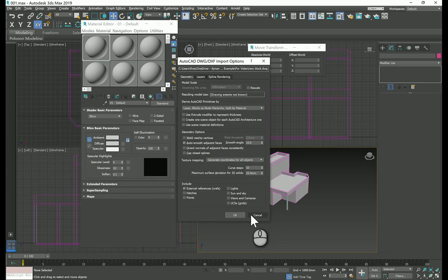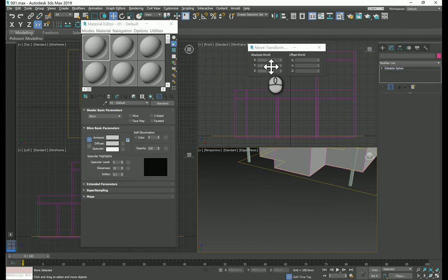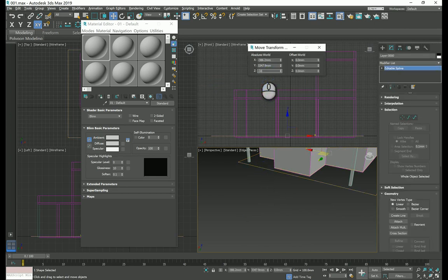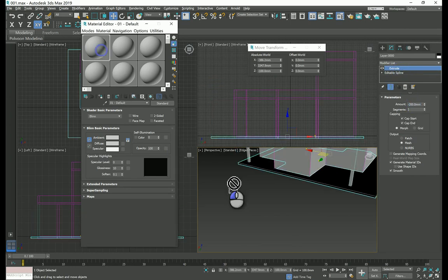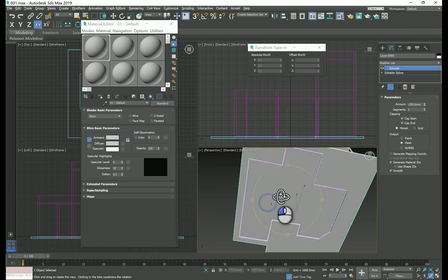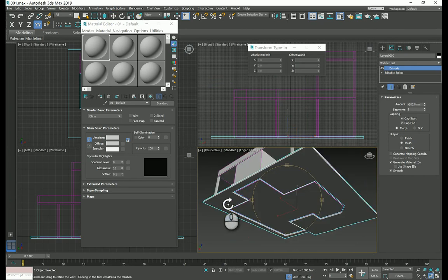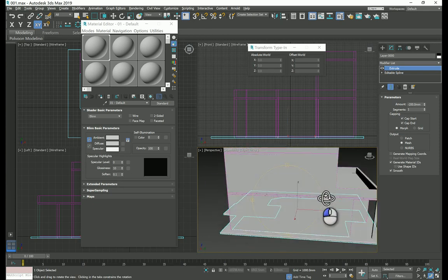So yeah. Again, this is minus 100, and also I'm going to paste minus 200. Drop the material for it, which is a standard one. Make sure that it's hollow from inside, because you don't need two slabs above each other. That's for the ground floor. This is for the walkway. In reality, it shouldn't be 200. It's like 100 mil. It's not a reinforced slab, so